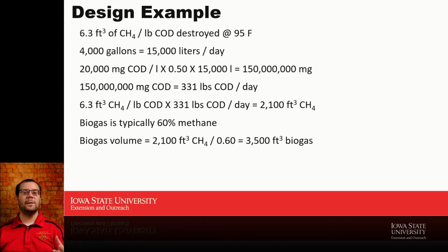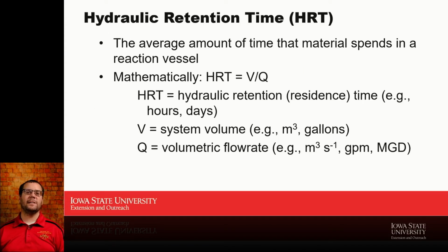Now, we might put some more sophistication in it, but that tells me roughly how big my gas cleaning system is going to need to be, how much I'm going to be putting in the pipeline every day, right? And how much CO2 I'm going to be off-gassing from this process, which really is a big part of how we design these things, how we make them work. The other is the size of the tank, and really that is based on hydraulic retention time.